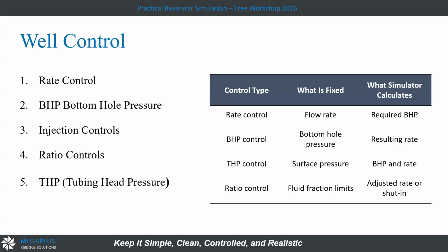Also the upscaling and the LGR. And before I go to a case study, the last thing in reservoir simulation is well control. I have to put the wells in their locations, and I can control the wells in the simulation by rate, bottom hole pressure, tubing head pressure, or wellhead pressure. So you can control by rate and simulate the pressure, or control by pressure and make the history match by rate. It goes that way.